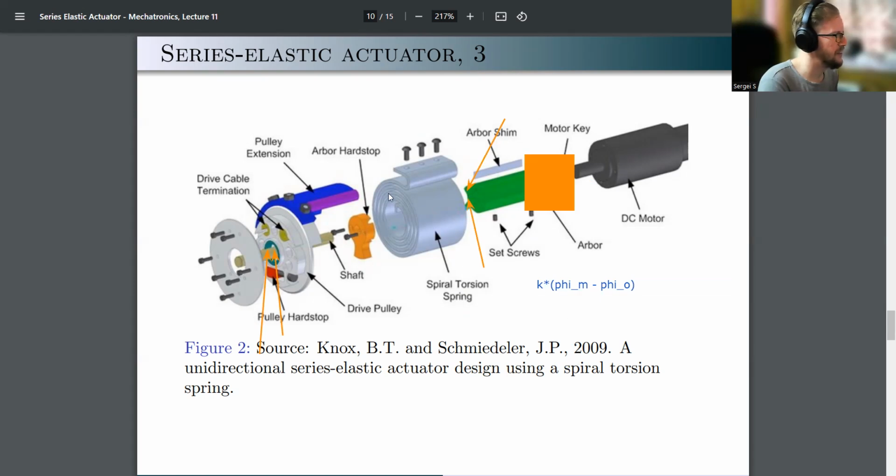So in this formula, unless you want to put gear ratio in front of phi m, which you probably don't want to do because there will be a whole lot of additional issues you could have. I mean, you could, of course, you just need to be careful. You probably would be better off just computing everything in terms of the same radians, so radians left of the spring, right of the spring. Okay, all right.